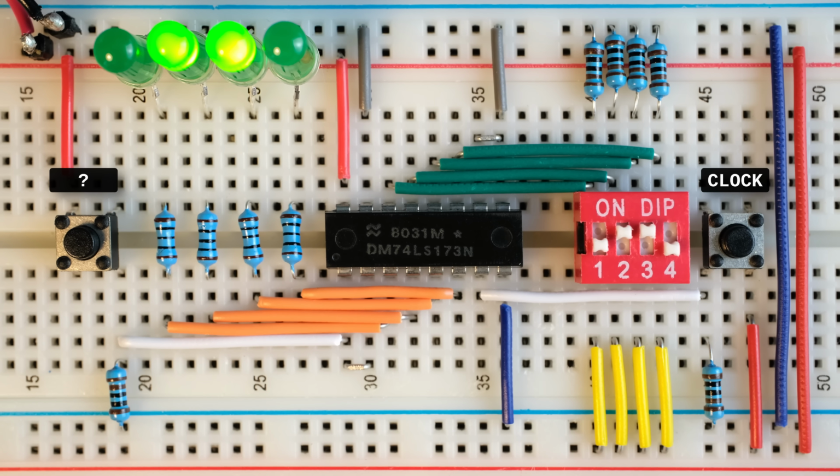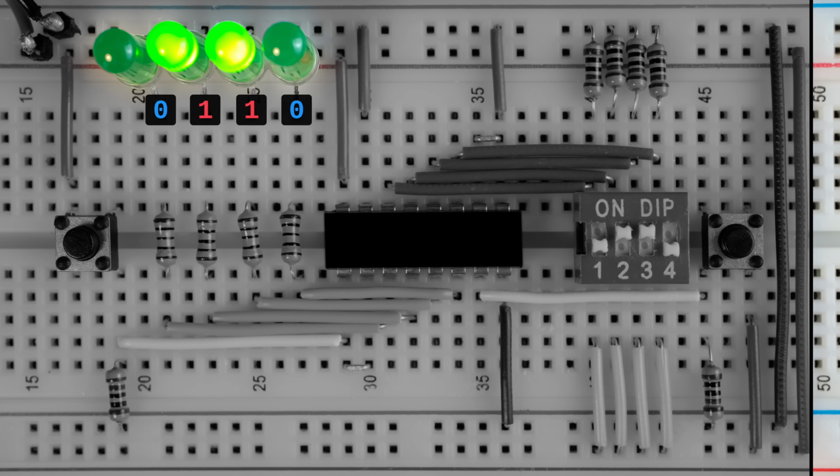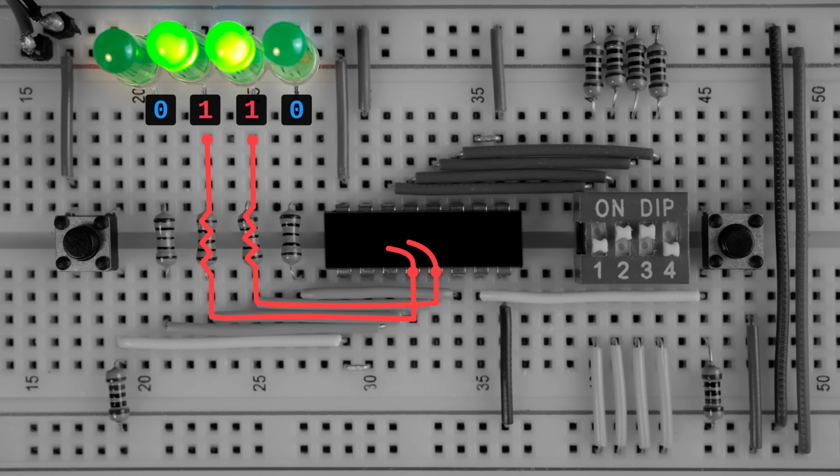Alright, that's looking good. So now the first thing I want to do here is just quickly remind ourselves what these 1s and 0s we're working with all the time actually represent. These little green LEDs are all connected to ground at the top, so the ones that are on must have been electrically connected to the power pin inside the chip, meaning that a 1 just represents a connection to a high voltage, somewhere around 5 volts in this case.